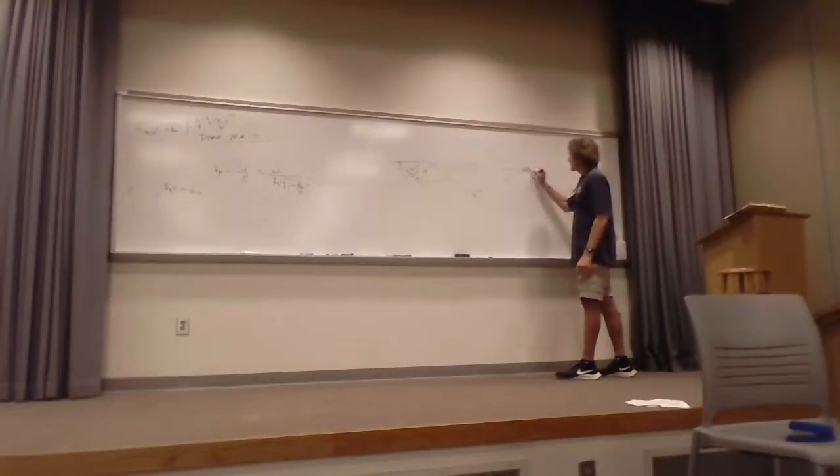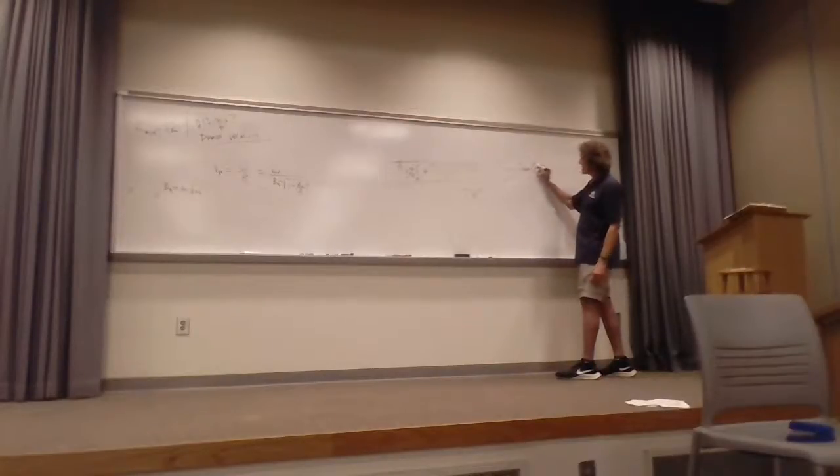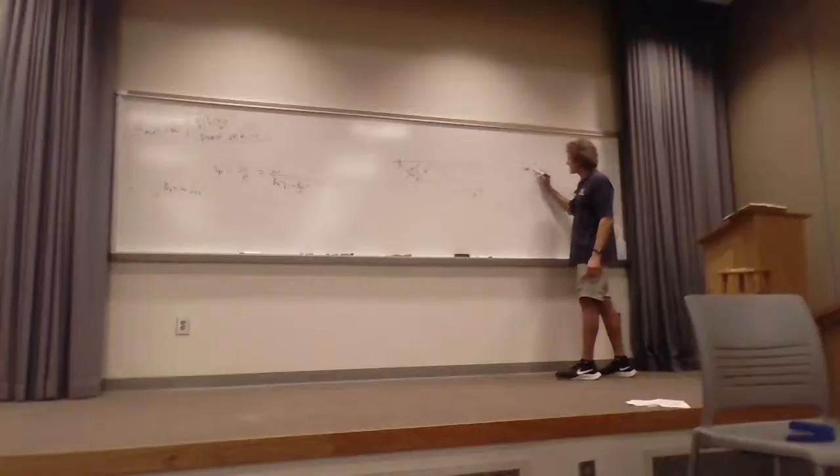But for a given distance traveled there, this would be a longer distance. But these would be the same phase fronts. Say this is 0, this is 180 degrees. Do y'all follow me? Now that point where it's intersecting and moving at a constant phase is the phase velocity, how fast it's moving.